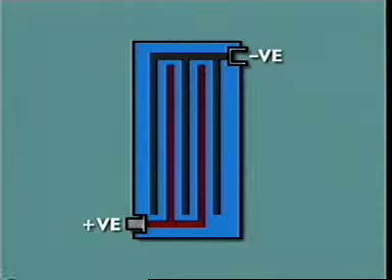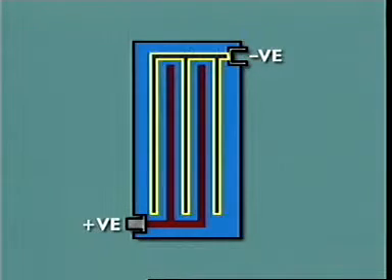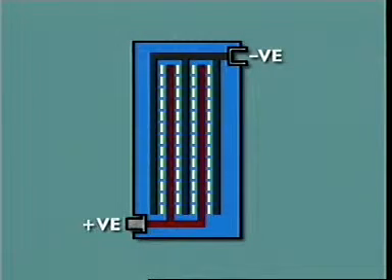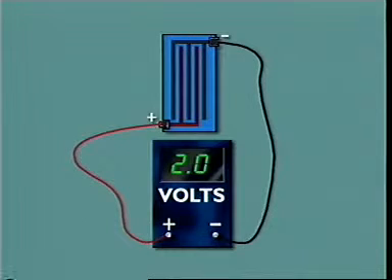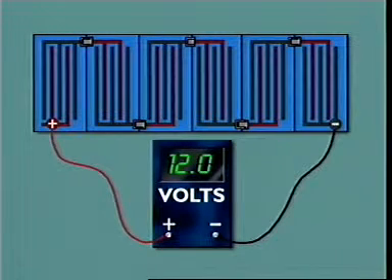In a lead-acid battery, the plates are assembled so there is always one extra negative plate. The plates are close to each other but do not touch, which would cause a short circuit. The nominal voltage of a cell is 2 volts. Cells connected in series make a battery, and the number of cells determines its nominal voltage.